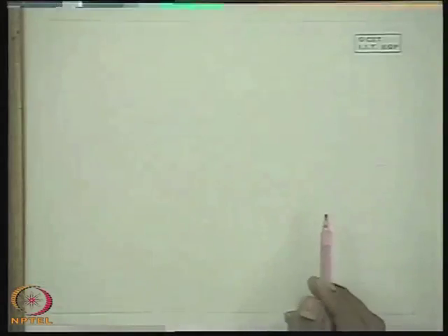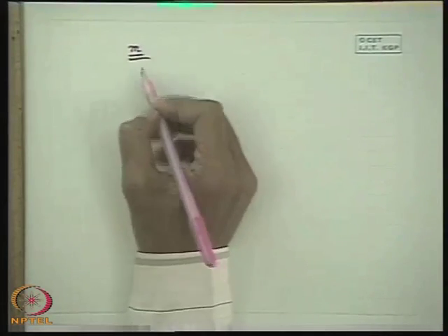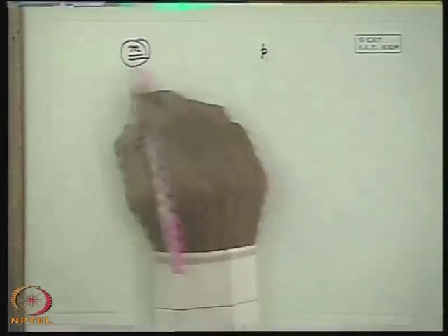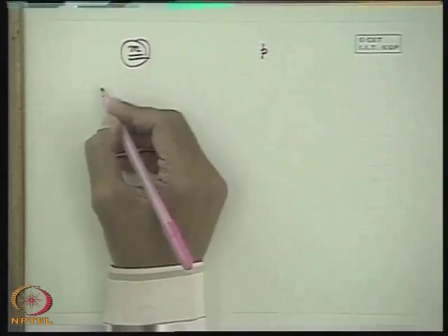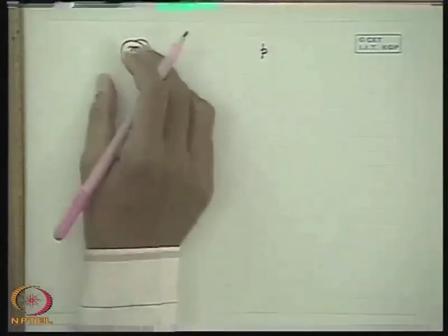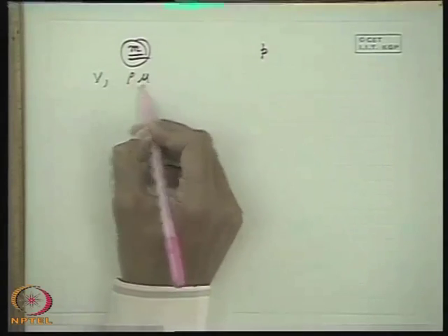Consider two systems, one in the laboratory and another in practice. The laboratory experiment is known as the model, and the actual case is the prototype, denoted by suffixes m and p. I can do the experiments in the laboratory under different conditions, choosing a different velocity, or a different fluid having different rho and mu.